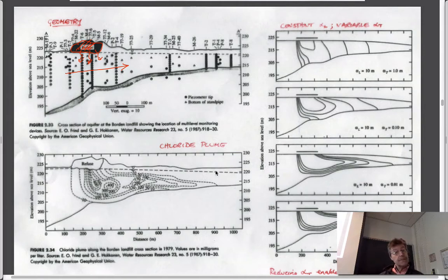I suppose you could surmise that as well if you look at the water table. The water table has a slight gradient to it, towards the left, I guess. Yeah, your left as well. But it's sloping down, so if you use Darcy's law, it would suggest that there's some velocity towards the right.